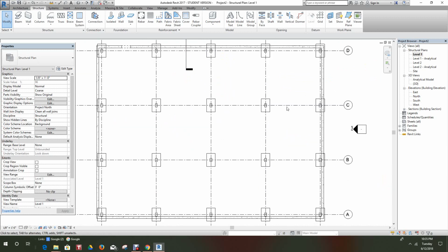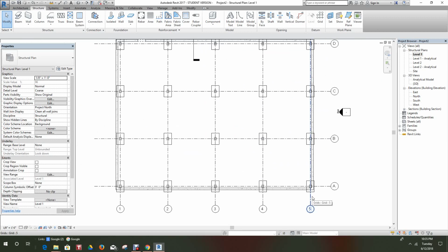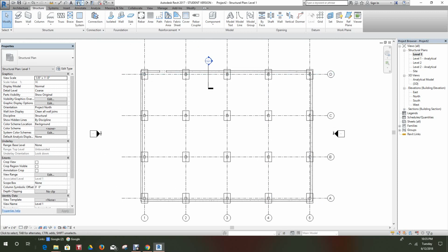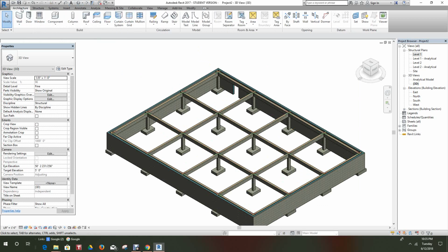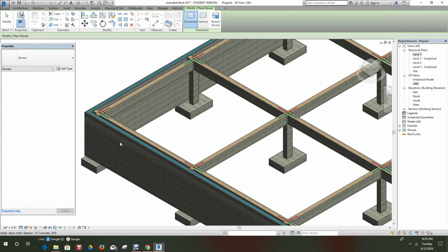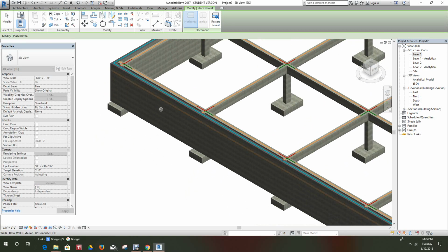Now, in the precast industry, they normally split walls and they have reveals and things. So let's go add a reveal quickly if I can. Let's go into 3D view, and let's go where it says architecture. I hope we have a nice default in here. I don't want to have to make one. Oh, come on. We go to wall, reveal. We got one here. Great. It's kind of big though. That's okay.